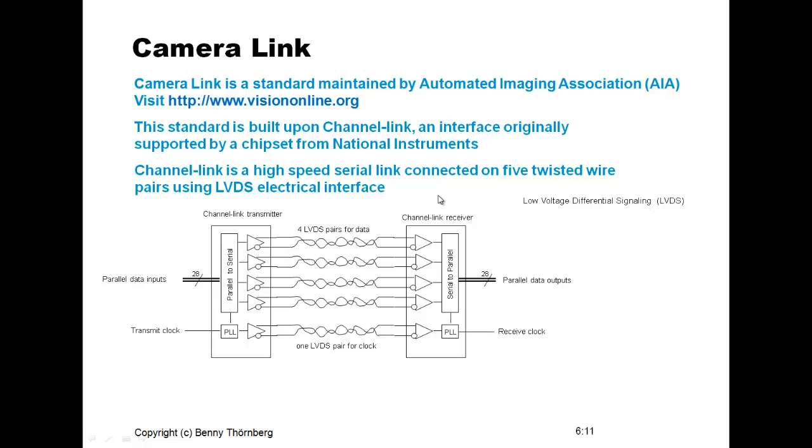It's a low voltage digital interface capable of transferring 1 bit of data using a pair of wires, and there is a matching of the impedance on the sender side and on the receiver side to avoid reflections and provide a reliable transfer also over large distances, also providing a large amount of noise immunity. And you see here that you have a transmitter chipset and you have a receiver chipset.